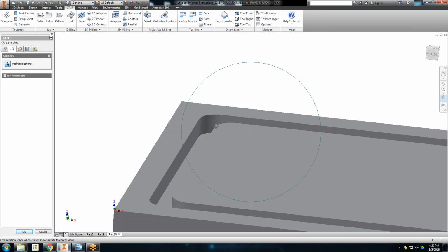It should, and that's one of the things I talk to the kids about. Because if I was going to do this in reality, and whoever designed this, engineered it, whatever, I should actually redo this. I should come into this corner and I should remove this little tiny part, because one way or another, if there's something supposed to fit down into here, I'm not going to machine it the way the engineer designed it. So in reality, I need to come back in here and I either need to contour it a second time or I need to attack just that corner, which I usually don't have my kids do. I have them go back in and do a redesign and fix that corner to be a true offset.